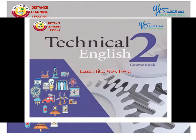They are, number one, linear motion. This is a movement in a straight line and in one direction. Number two, oscillating motion. This is swinging from side to side. Number three, reciprocating motion, which is a movement forwards and backwards or up and down. And the last one is the rotary motion, which is a circular movement.